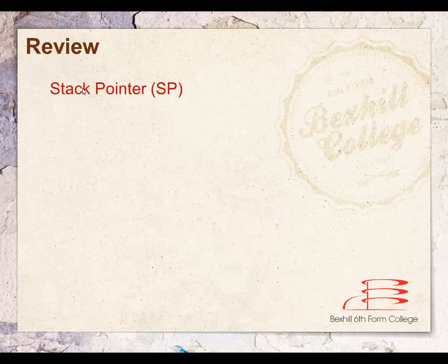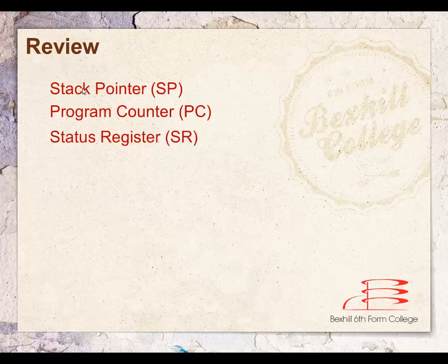We've looked at the stack pointer and that it points to the top of the stack. I've explained what the stack is, that it holds the values of the functions and formulae of your variables as you're going through, plus addresses. Program counter we've seen holds the next instruction. We've seen how that works in the fetch execute cycle. Status registers, as I say, I've mentioned predominantly the carry, but there are a number of other registers in there. They're either general purpose or they are ones that have a specific role within the processor.